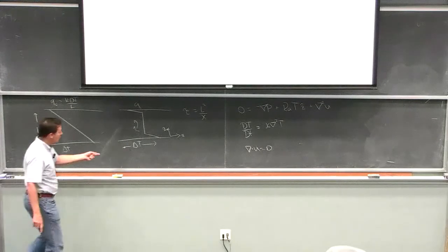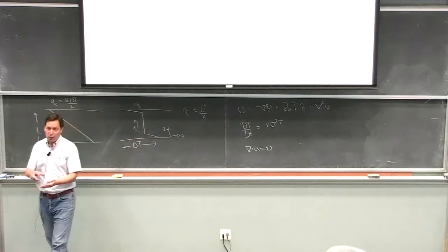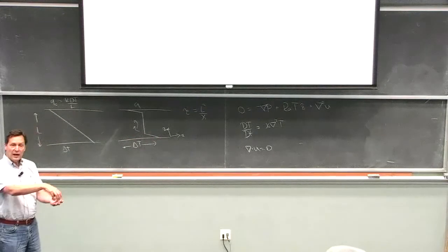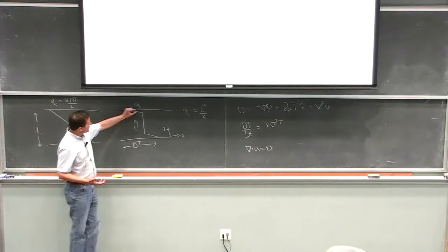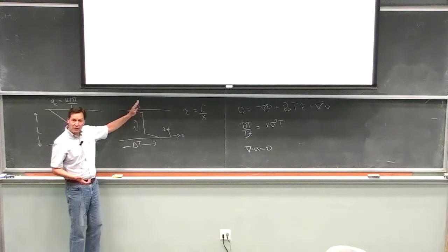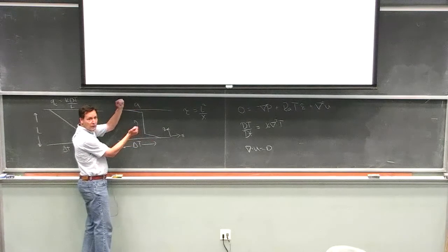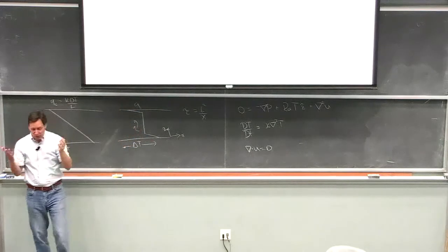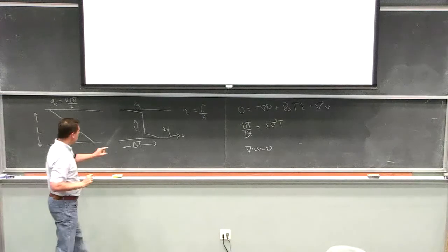And the same thing is probably happening at the bottom, this bottom thermal boundary layer. Fluid is getting hot, it's heated up, it gets buoyant enough to become unstable, and it rises up, okay? And so you could make the assumption that the processes going on right here, in terms of forming these drips and having them sink down, are largely independent of what's going on at the bottom boundary. A reasonable assumption, I would claim, is that what's going on at the top is really determined by processes in the vicinity of the boundaries. And the same thing at the bottom.